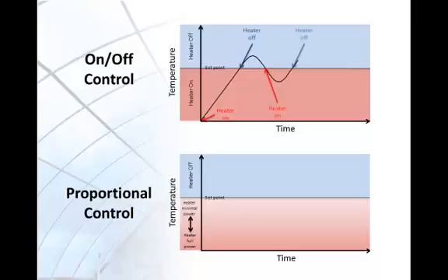You can see the oscillation in temperature about the set point as the heater is turned on and off. A deadband or a time delay can prevent equipment from cycling on and off as fast, but may increase environmental oscillation. Data averaging does a good job of reducing on-off cycling without necessarily increasing oscillation, but will not eliminate oscillation. Multi-stage control will do a better job smoothing out oscillation, but will not eliminate it completely, as turning on and off additional control measures will cause sudden fluctuations.